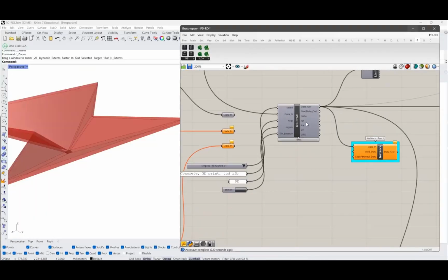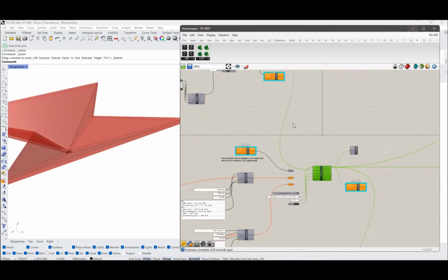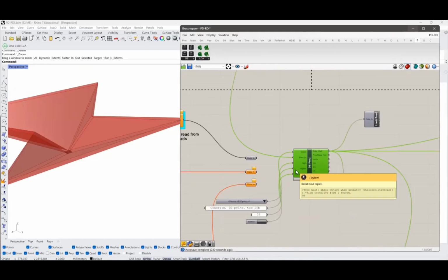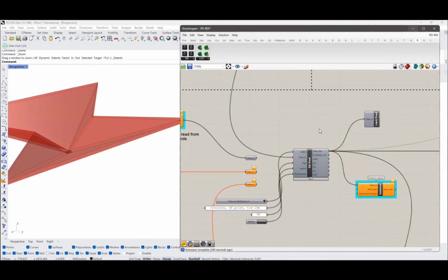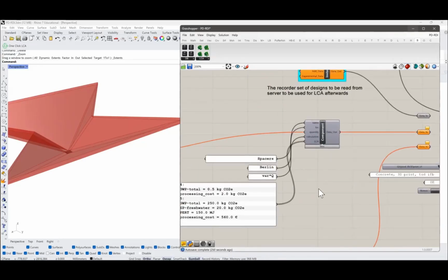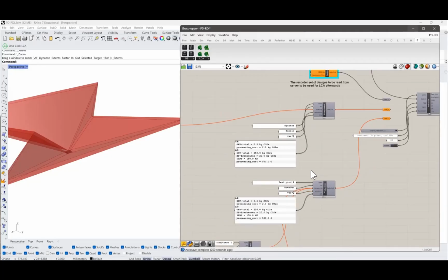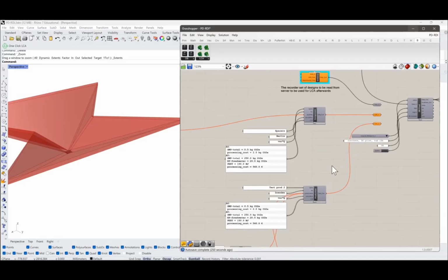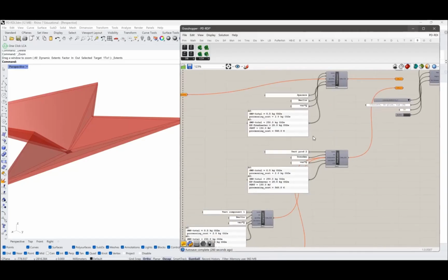So then after the production, let's make another example where we produce the shell. We have a concrete, we have a textile, we use them from the model assembly, but we may have other components to produce this element. For example, formwork, spacers, and other special features that are not needed in your main model, because for the structural analysis you do not need all these special components, but they affect the production and they affect the LCA output. That's why you also model them.